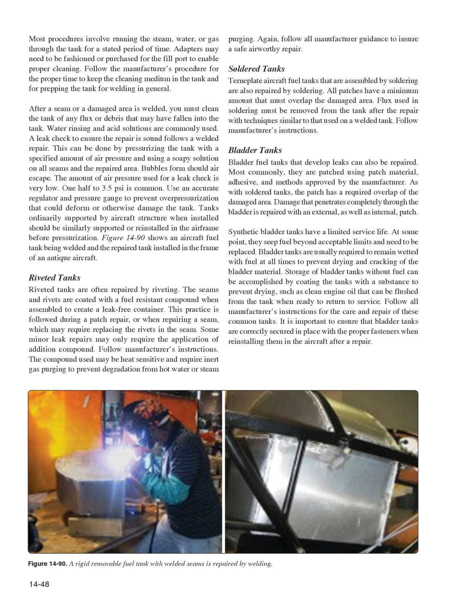Bladder fuel tanks that develop leaks can also be repaired. Most commonly, they are patched using patch material, adhesive, and methods approved by the manufacturer. As with soldered tanks, the patch has a required overlap of the damaged area. Damage that penetrates completely through the bladder is repaired with an external, as well as internal, patch. Synthetic bladder tanks have a limited service life. At some point, they seep fuel beyond acceptable limits and need to be replaced.